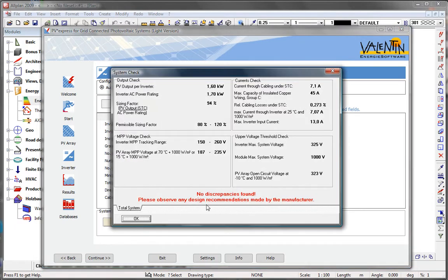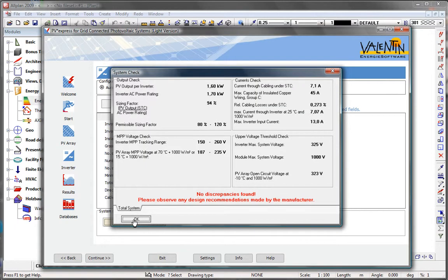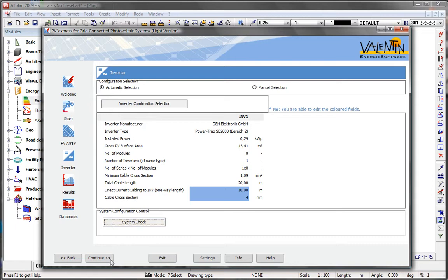You test your entries easily with the installation check. The system checks whether your installation components are well dimensioned and connected. It also checks performance, currents, idle running, and MPP voltage. The corresponding dialog provides detailed information on possible incorrect adjustments.